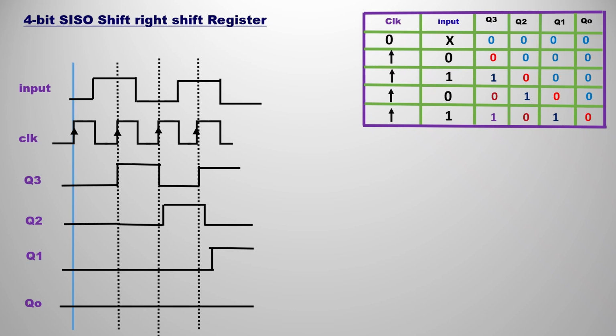Now you are going to draw Q3, that is 0 1 0 1, according to the input. Then according to Q3 we are going to draw Q2 also. If you see Q2 in the truth table, it has only one 1, in the third position, so draw that only one. Q1 has only one 1, in the last position, so draw that. Q0 doesn't have any ones, so it is plain. All the levels are 0 in Q0.